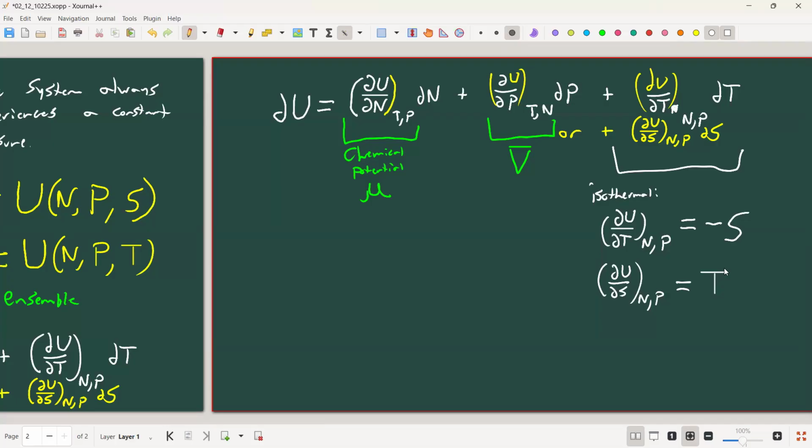All right, but we can go a little further than this. This isn't all that helpful. Because one of the problems, and Angie's comment kind of tackles this, is that pressure and volume in some sense are not particularly well-defined quantities, especially pressure, for liquids. Liquids don't expand or contract very much. They have a density. That density is temperature dependent, but it's not really pressure dependent. It's very hard to make water more compressed when it is a liquid. And so it's not the best variable, right?